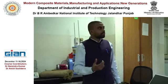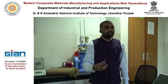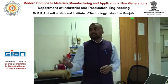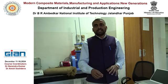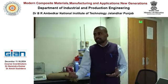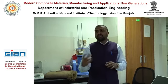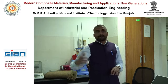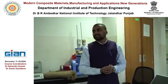Definitely we have to do that. For example, if your composite is used in the superstructure of a ship, the environment is different. Your composite may experience humidity. Your composite experiences seawater, right? Salts. So again you have to test for that particular environment, so that it will sustain in the real life application.